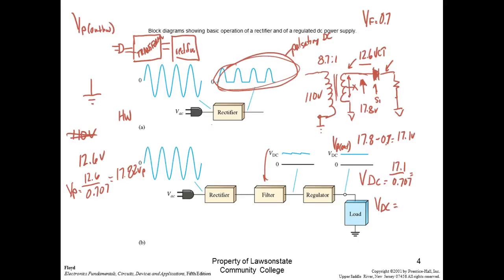So this is why it's imperative that you put the right voltage on a device. If you put the wrong voltage on there, you're going to have problems with power. A motor, if you didn't put enough voltage on it, might not generate enough power to start, and then it would burn up, which is strange. I mean, it's because it's not producing something that it's supposed to be producing when it starts rotating. So yeah, if I went to a different transformer and hooked this up, it might burn up this resistor.